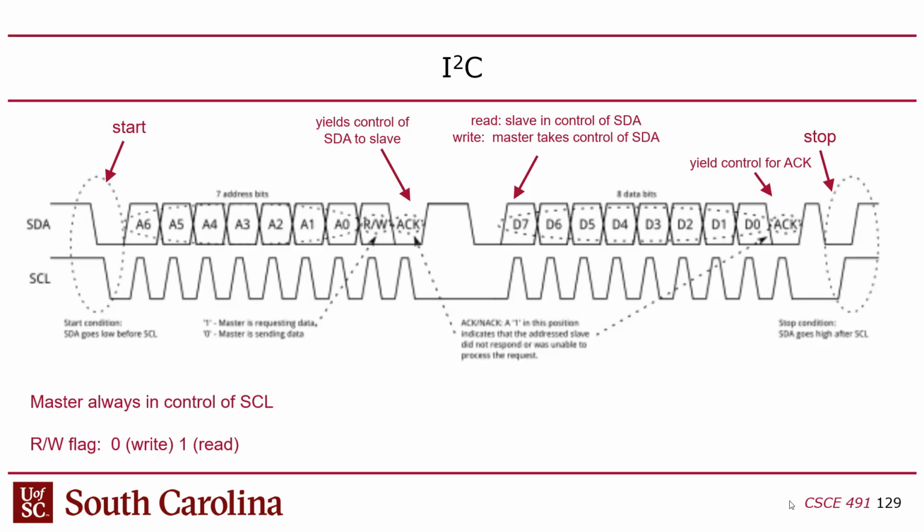And you might say, well, why is that such an extraordinary thing? Well, it works into this open drain thing, right? Because basically these signals are only high when no one's doing anything with them, and they're low whenever anyone on the bus happens to be pulling them down. So whenever the data is being sampled, it can't be sampled until everyone lets go of the bus, essentially.